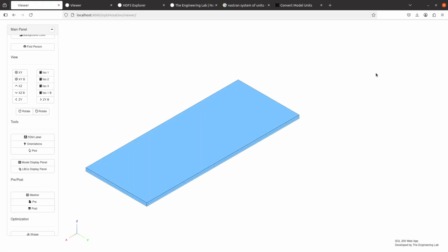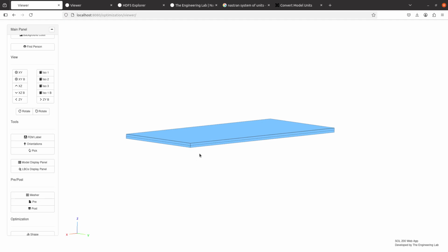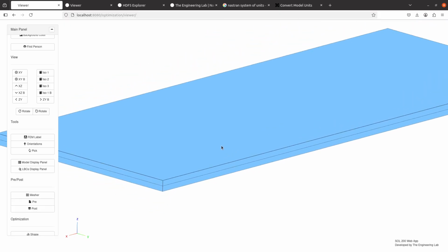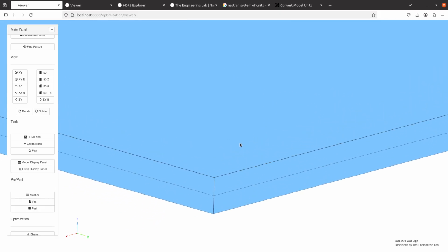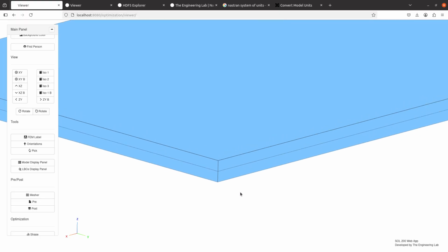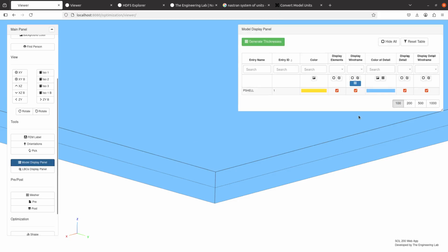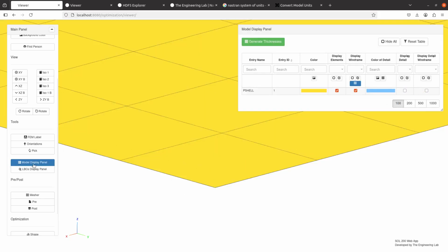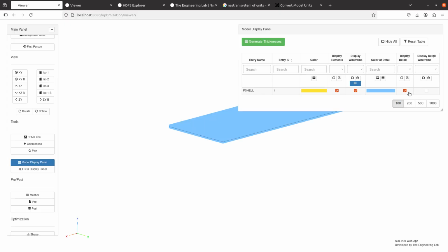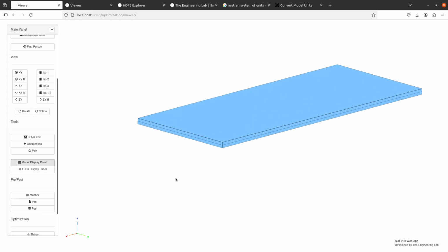When you do this, back here in the view, if you will, we actually get a preview of what the thickness looks like. Whenever you're dealing with these C quad 4 elements with the P shell entry, notice that we have our elements here, and then we have a thickness like you see here.